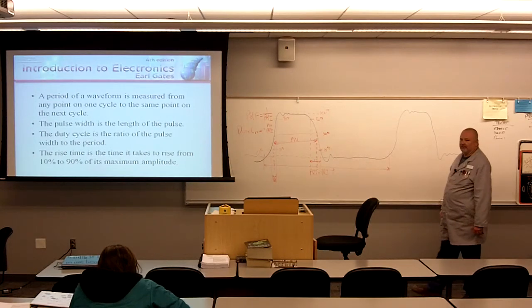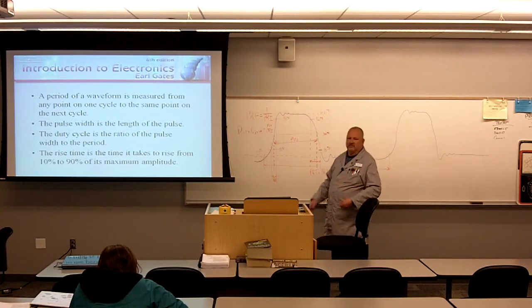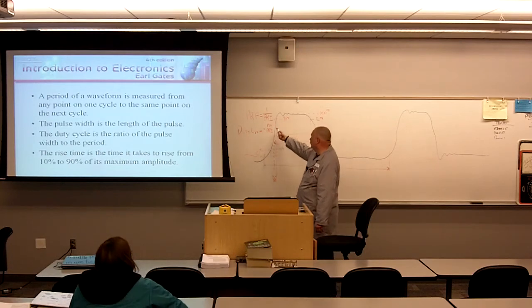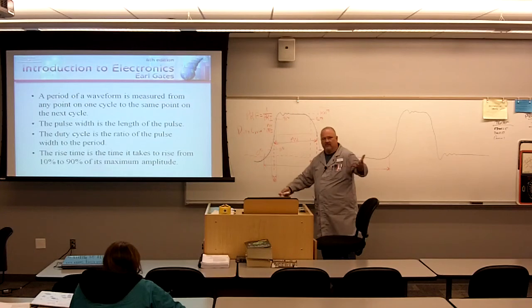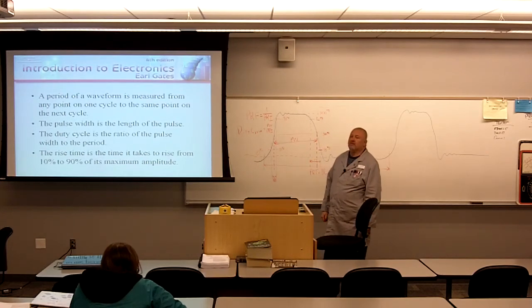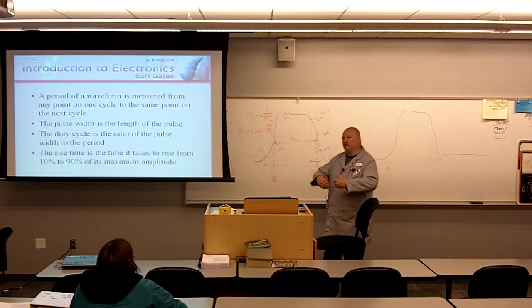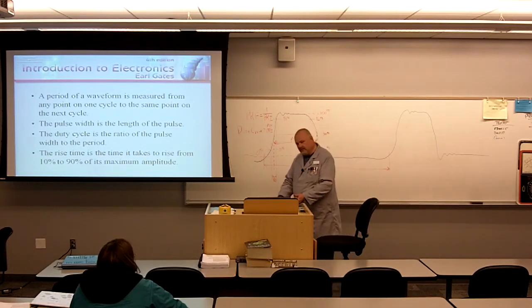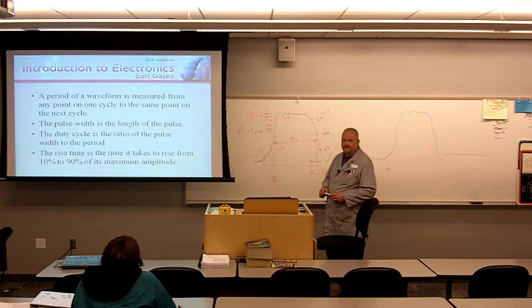But I was trying to accentuate that because sometimes there are idiosyncrasies in the circuits that cause this. Sometimes your rise time, as you're building up the pulse, may take longer. Then the pulse gets spit out, and then it drops faster. It's the idiosyncrasy of the circuits. The bottom line, the reason we're sharing this with you today, is that you've got to be able to articulate that and measure that on your equipment. You have to know what it looks like beforehand, and then when you're troubleshooting the equipment, determine whether this is a problem or not.